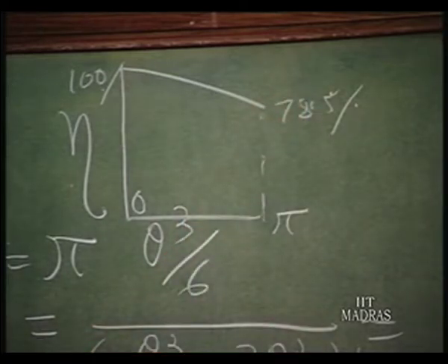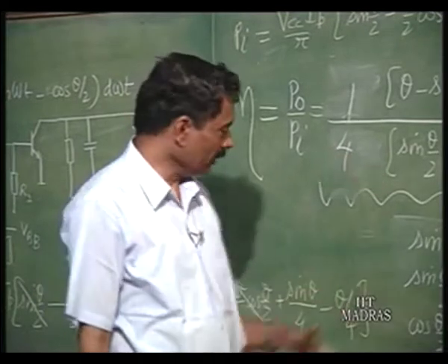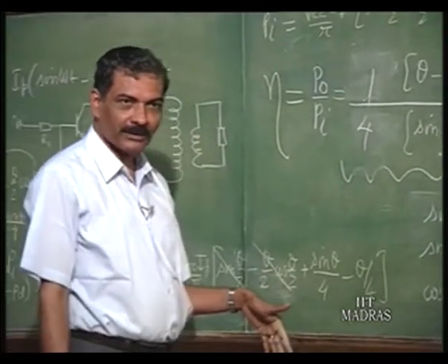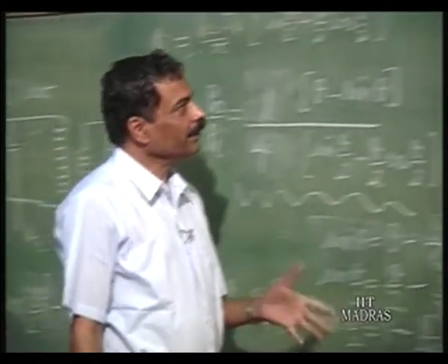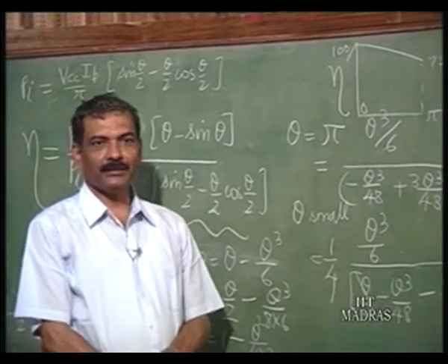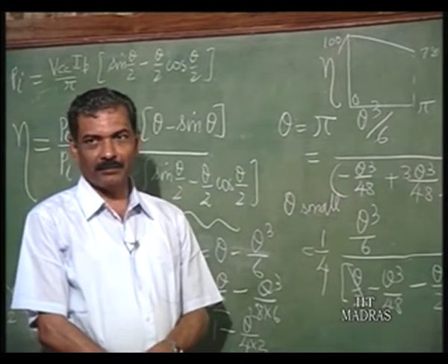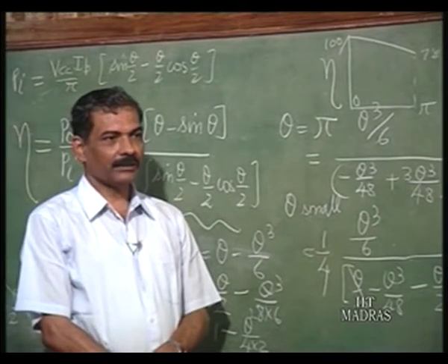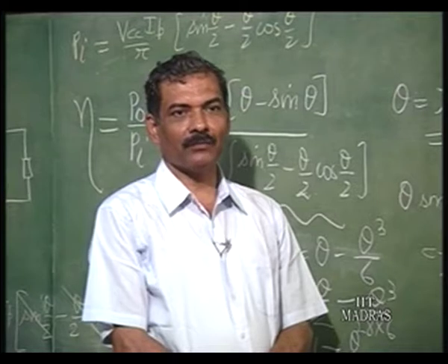Now, this is the maximum ever possible efficiency under the assumption that we have swung almost up to the minimum which is 0, etc., and therefore, these are all not valid, and therefore, efficiency is typically of the order of 70 to 80% for a practical class C power amplifier, which is going to deliver a useful power of about 200 watts.